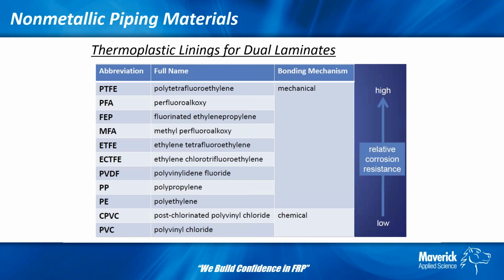So there are cases where we may not require it, unless we see a lower Barcol hardness or some other issue with the resin cure, and we want to make sure that it's cured all the way through to meet our expectations of hardness. That would be the other option. But generally, you want to say it's required or not, and it's only optional if you're not meeting some sort of hardness criteria or something along that line.